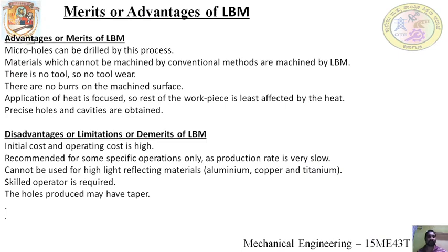Then, advantages of laser beam machining. Advantages of laser beam machining are: micro holes can be drilled by this process. Materials which cannot be machined by conventional methods are machined by LBM. There is no tool at all, and there is no tool wear.